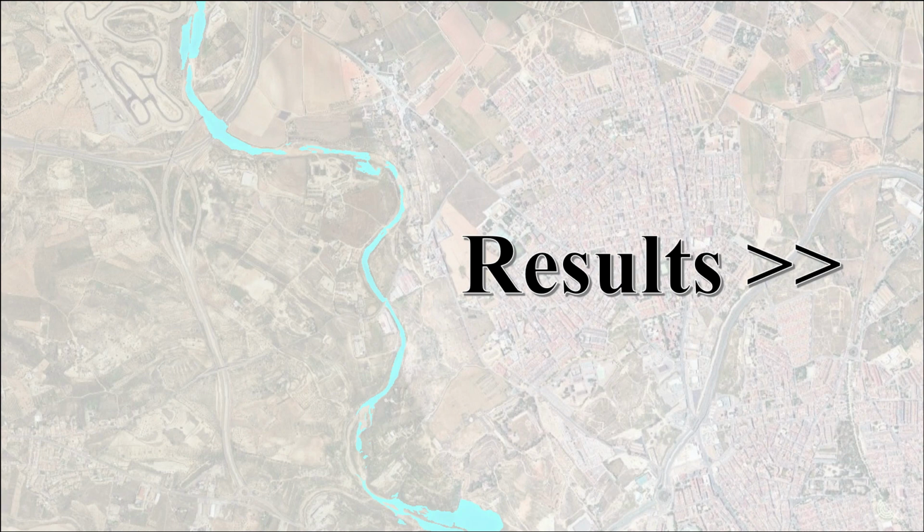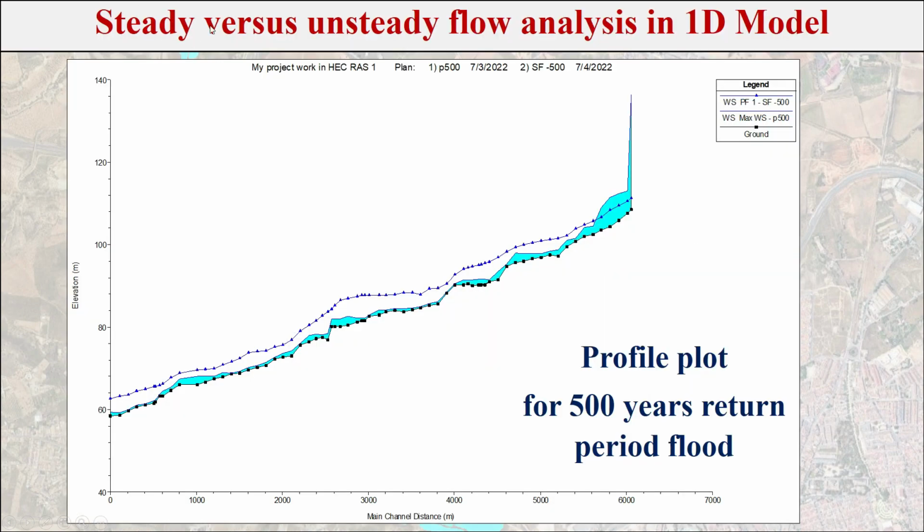Now let's look at the results in different terms: depth, velocity, and flood inundation. Before comparing the 1D and 2D models, first we analyze steady versus unsteady flow in the 1D model. For the 500 years return period flood, I plotted the profile. Here you can see the upper line is for steady flow, and the lower one is for unsteady flow, and this is the bed level.